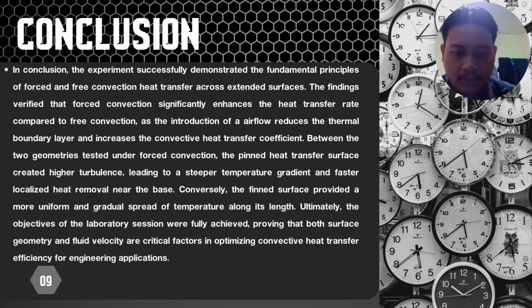Regarding the geometries evaluated under forced convection, the pin surface induces greater turbulence, resulting in a more pronounced temperature gradient and accelerated localized heat dissipation at the base. Conversely, the fin geometry facilitated a more uniform and gradual thermal distribution across its entire span.